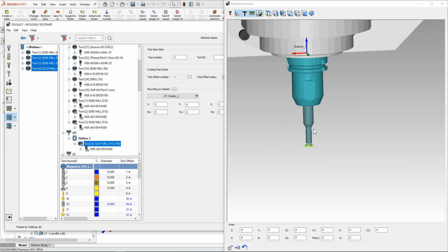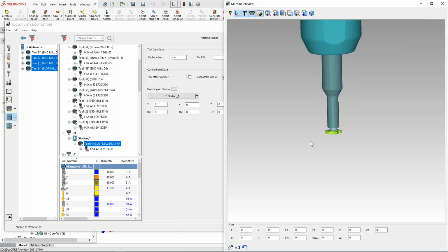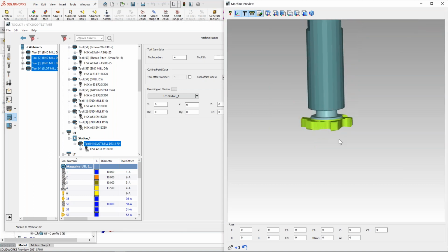But there's one thing here. It's connected to the question that I got, like how we can use the insert cutters and mills, indexed end mills, it's called. I'll just show you right now. But what is a very important feature there? As you can see here, this is real solid, but they are not revolved. In the simulation, of course, it will be revolved, but I want to see it also in SolidCAM.